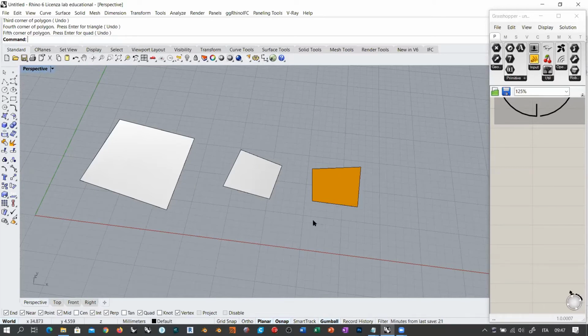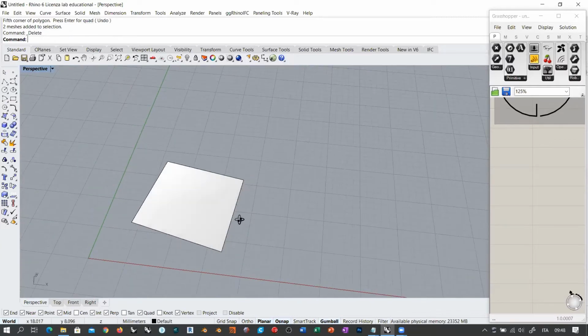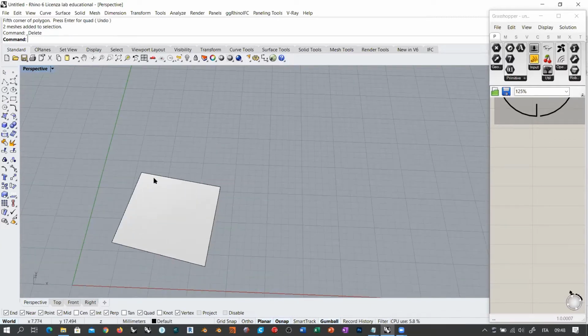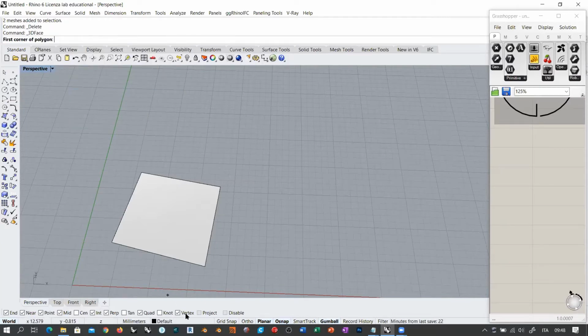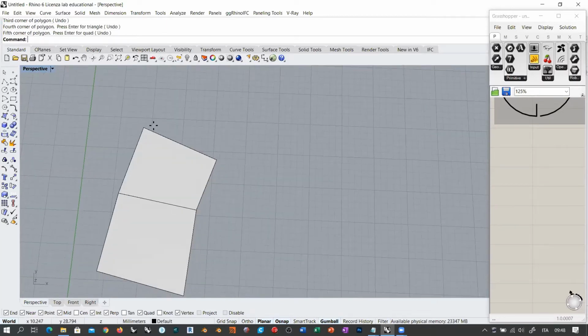In Rhino, all of these things are mostly irrelevant. In Rhino, meshes just play a role when you create renderings. But we want to base all of our workflow on meshes, so we must clearly understand how to adjust mesh objects. We will not be creating meshes in Rhino, because just think about it. If I want to create a mesh in Rhino controlling the topology, I should start creating single mesh faces with the vertex snap turned on, so I can snap to the actual vertices of the existing polygons, and create the mesh polygon by polygon.